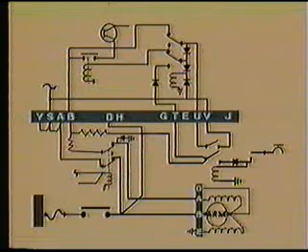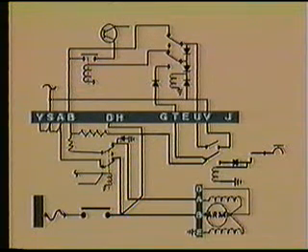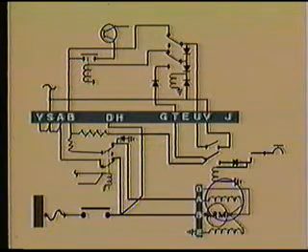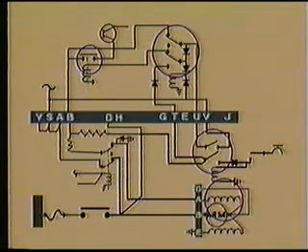After the generator has been disconnected from the line because of a fault condition, or if the generator residual voltage is not sufficient to produce a generator output, it will be necessary to perform the reset function on the system. When the system is reset, the generator field will be supplied power to flash it, and several relays will be energized. The effects of each of these actions are as follows.